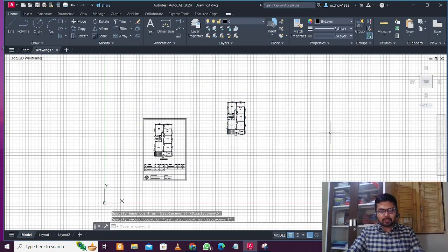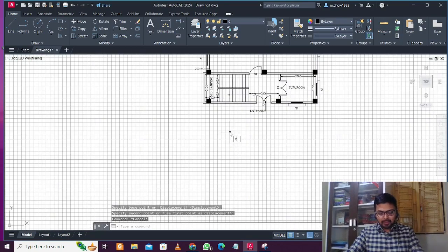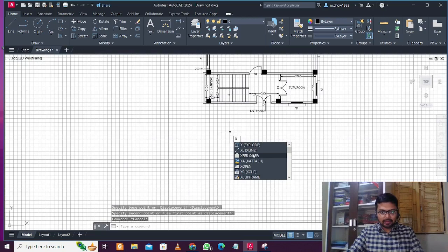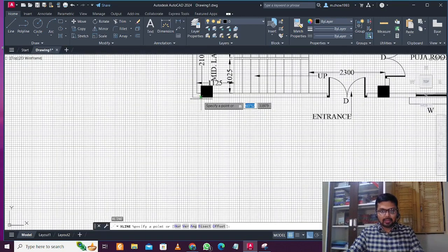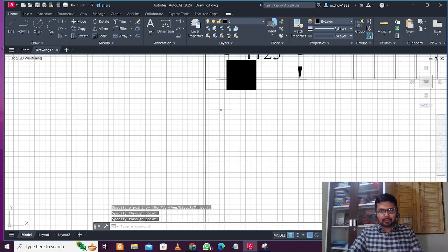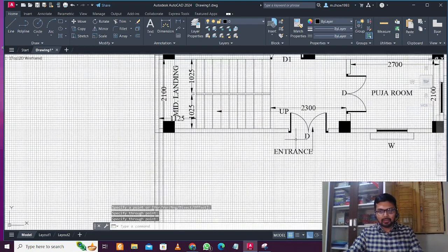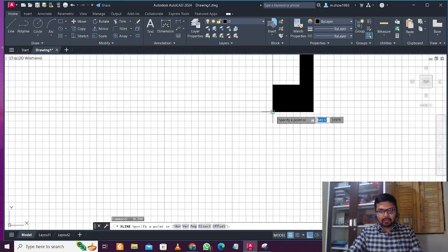I'll just make the elevation out of it. So move it a little bit forward, and we'll use the XL lines, the X line command, just to draw out the elevation from it. First of all, for the front elevation, all the significant commands and things are drawn out.